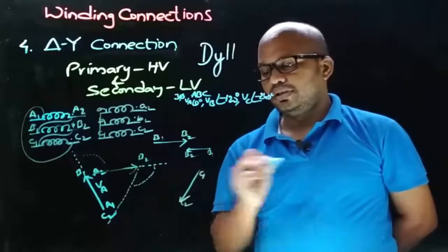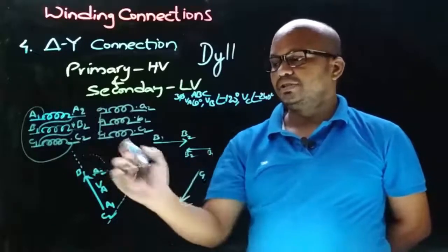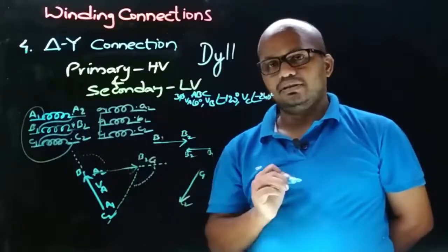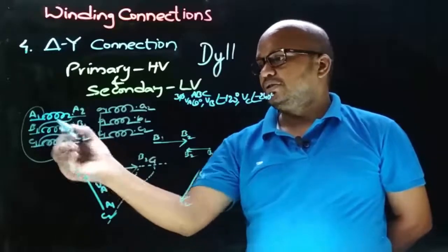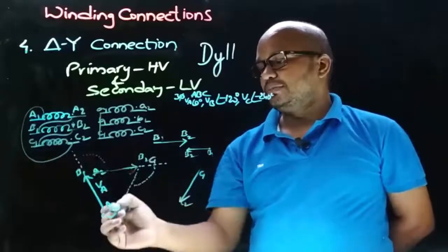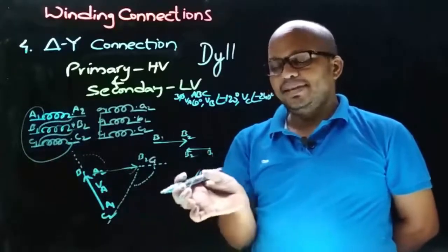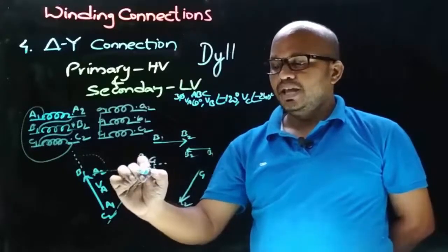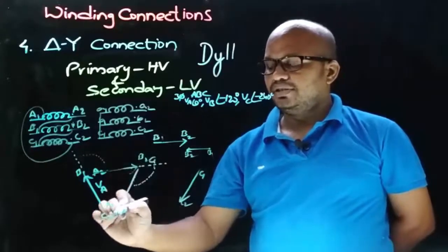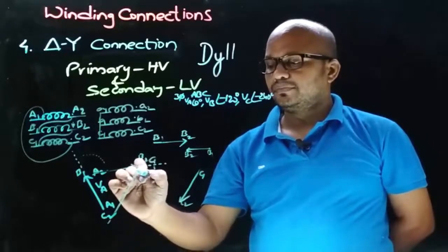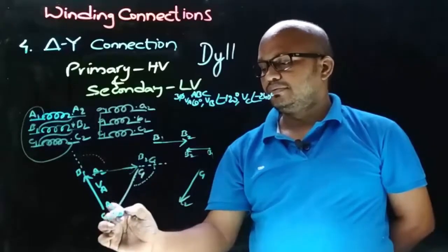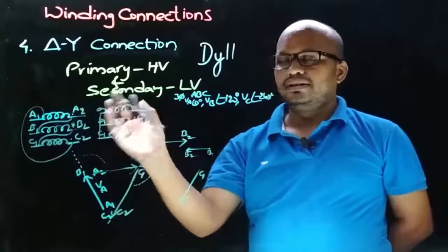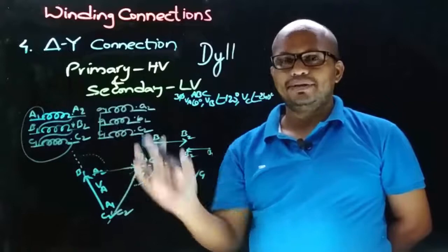like this. Now observe the winding connection, that to B2 there is the C1 connection, meaning here we must have C1, and to A1 there is the C2 connection, meaning here C2. Therefore, place this phasor here such that B2 will have C1. Therefore, this is the phasor diagram for the delta connection on the primary side.